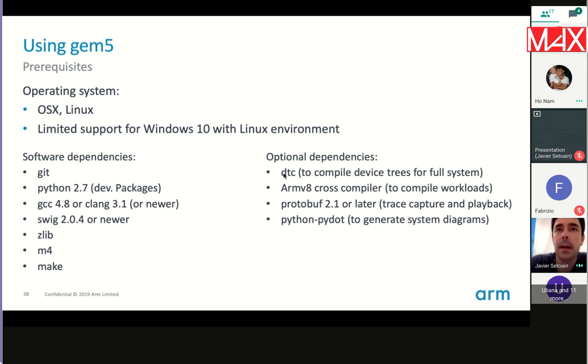Everything has to be predefined in this device tree that tells the operating system kernel what's where, and there's actually no way around this, because the thing with ARM is that, again, partners will implement their own systems, so you can't have a generic detection system. This is the best second option, and you will have to deal with that if you want to do your own full system thing.